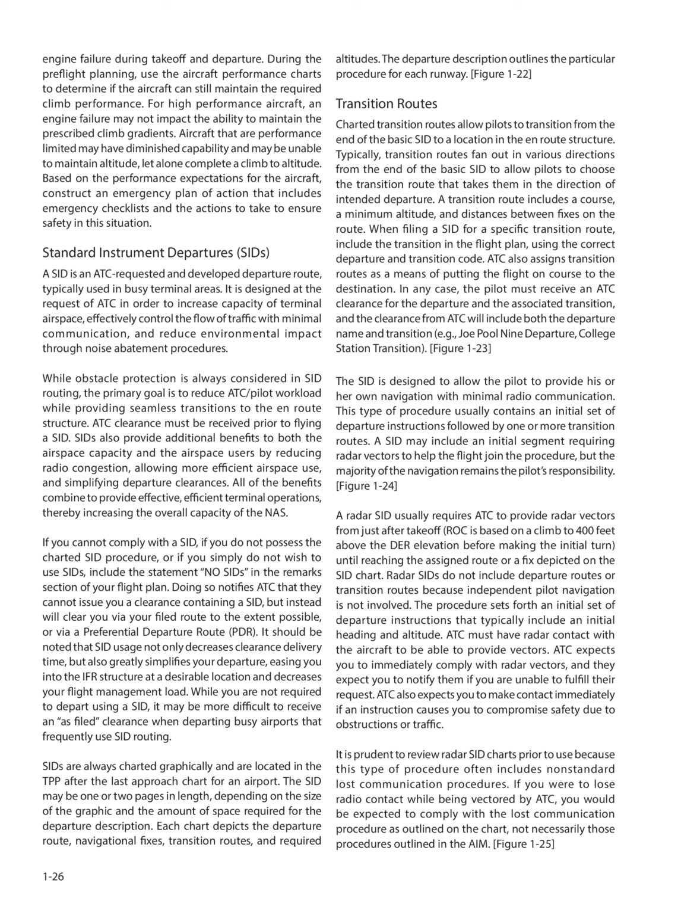If you cannot comply with a SID, if you do not possess the charted SID procedure, or if you simply do not wish to use SIDs, include the statement "No SIDs" in the remarks section of your flight plan. Doing so notifies ATC that they cannot issue you a clearance containing a SID, but instead will clear you via your filed route to the extent possible, or via a preferential departure route, PDR.